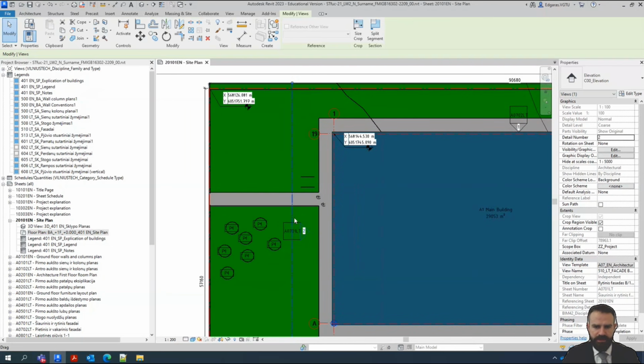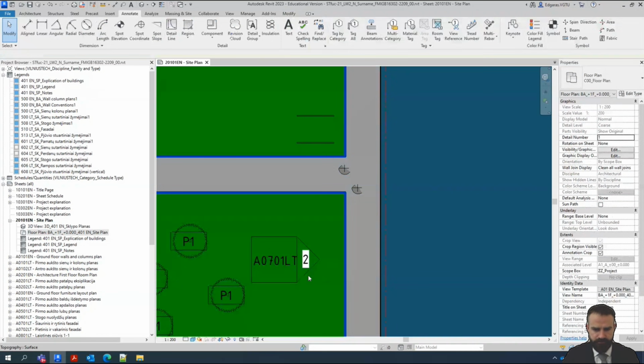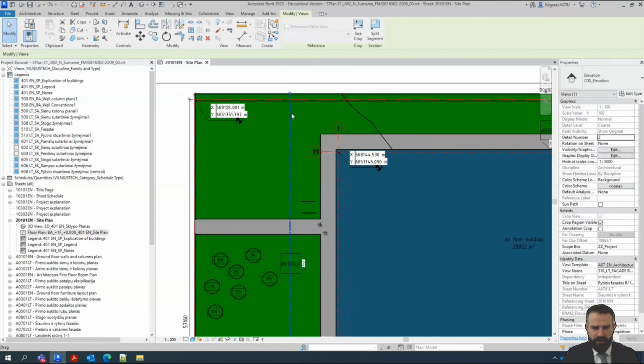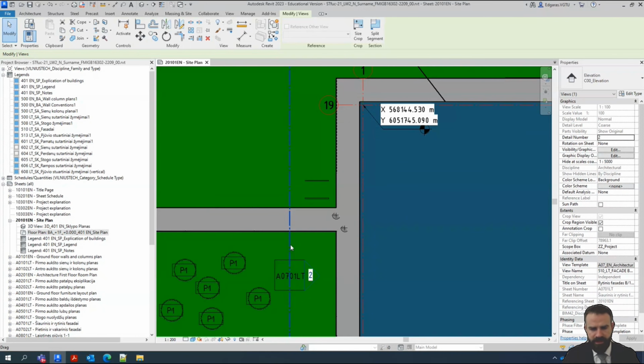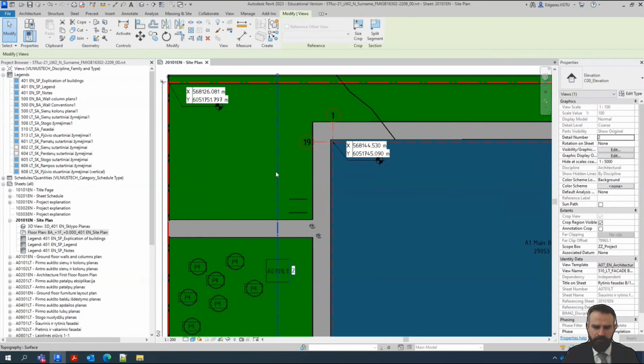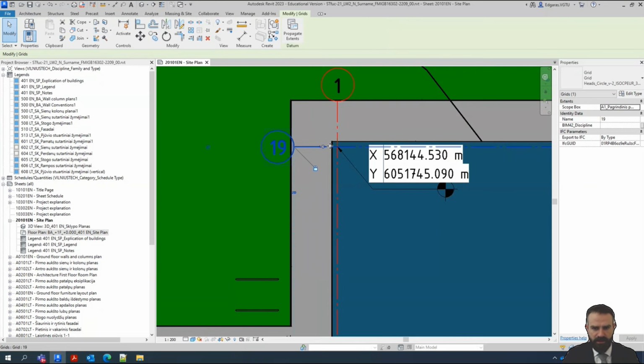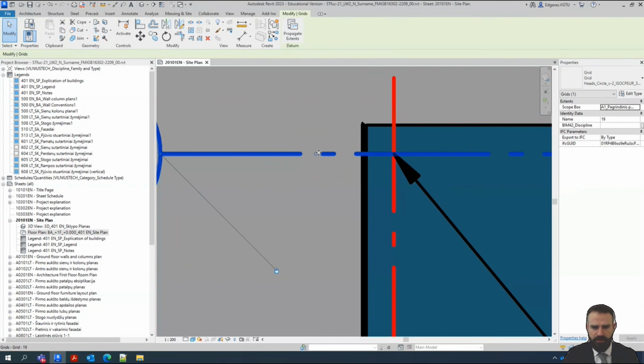Now the facade symbols. If you click on the triangle, you will see a blue line. This blue line represents your facade section location. So if you want to see grid lines or other elements inside the facade, you should move this line to the position in which grid lines have 3D representation. So my grid lines 3D object is represented here.